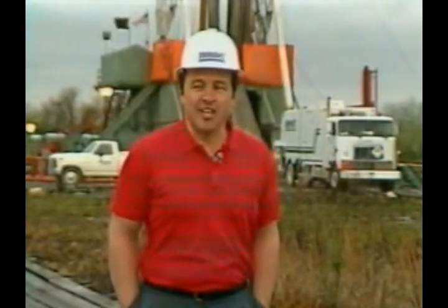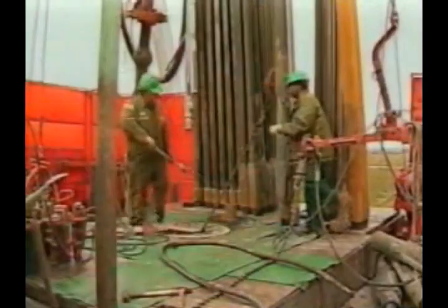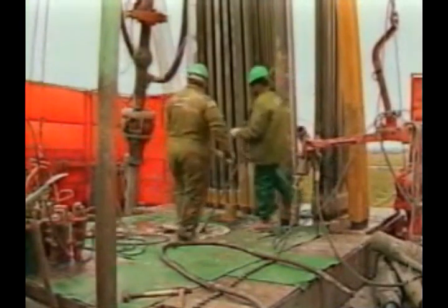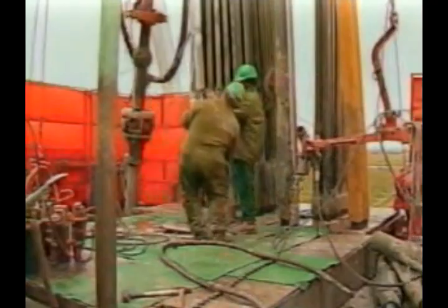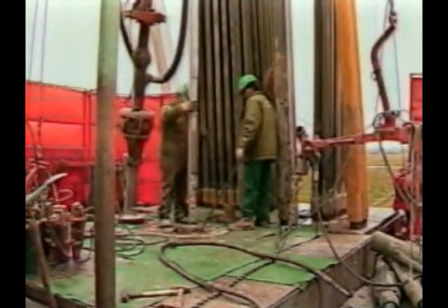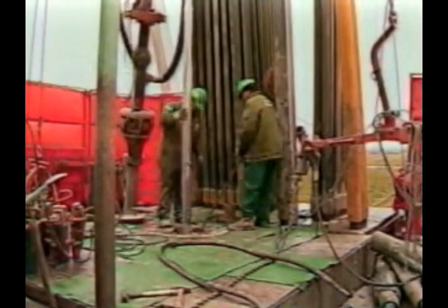If the survey includes a radioactive device, the last step in preparing to log is now taken. The rig floor is cleared of any non-essential personnel, and the radioactive sources are placed in the tool. The hole should be covered during this procedure to ensure that the sources do not fall into the hole. After the sources are inserted, the tools are lowered into the hole. With all logging devices now tested and operational, the logging phase can begin.